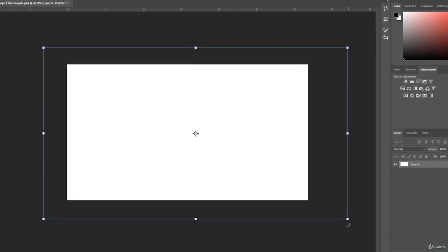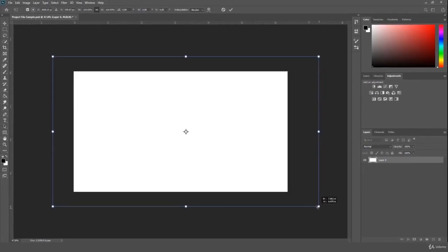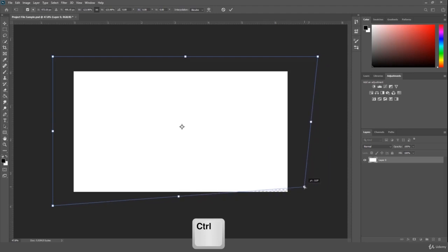Now, alternatively, if you wanted to get into a more advanced adjustment or change the shape further, as you see, these are locked edges. So if we click on the edge, it changes the whole dimension of everything and scales it in and sort of locks the dimensions. But if we hold Control before we click it, we then click on this point and we have a little bit more leeway, if you will.